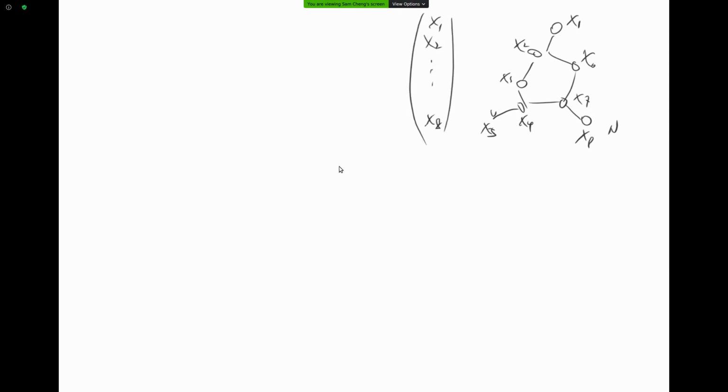So I can have a linear graph filter. It would be like this: I have the original signal, then I multiply by a matrix, and I have the new signal here. We can also mention the extension of the Fourier transform, from classic signal processing to graph signal processing.